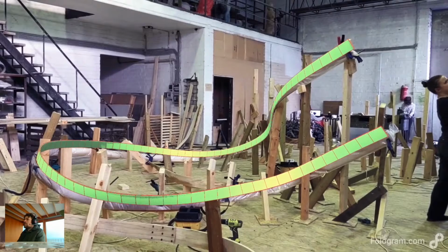So you whack on a headset, you see where the hologram is, and you start putting down these pieces of timber just so that they match the shape of the strip at any one place. And it also let us work within the tolerances of the fabrication process. So when you're steam bending these very long pieces of timber, because the timber itself is floppy, you don't need to make something exactly accurate. This needs to be accurate to within a couple of centimeters, but any more than that, and it's not actually worth pursuing just because of the flexibility in the material.